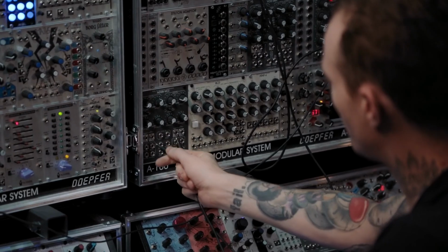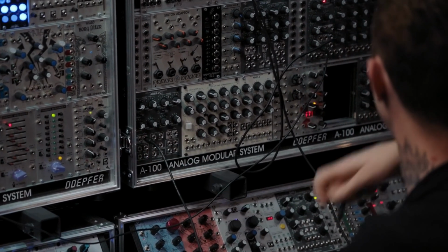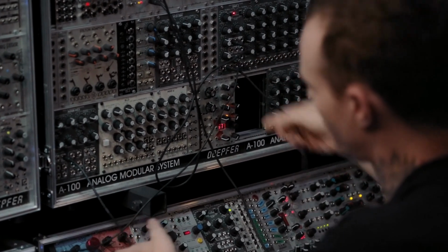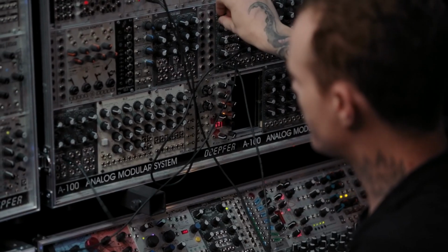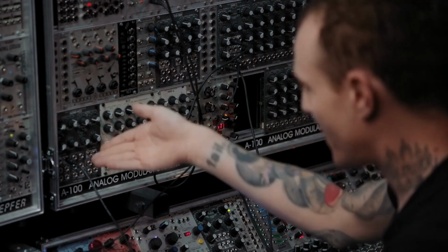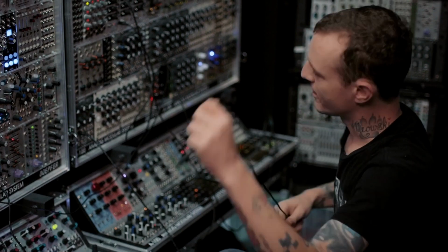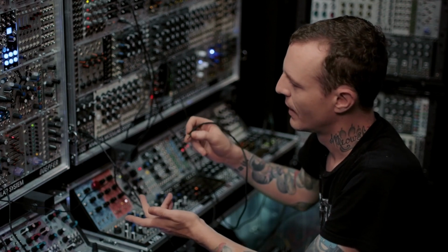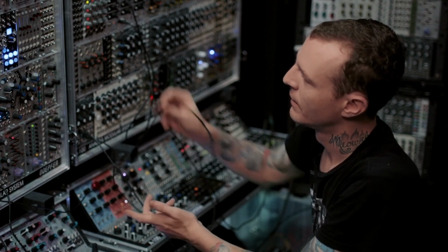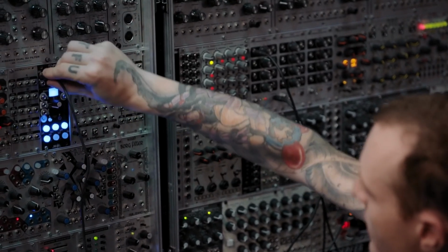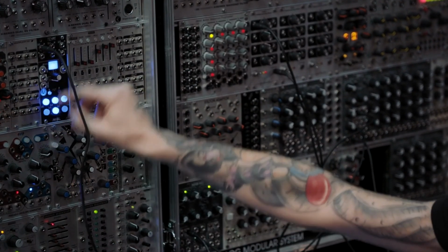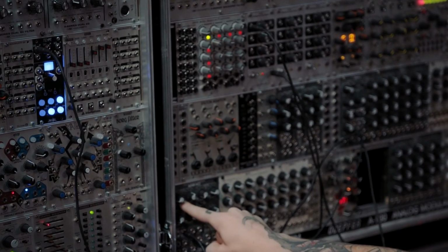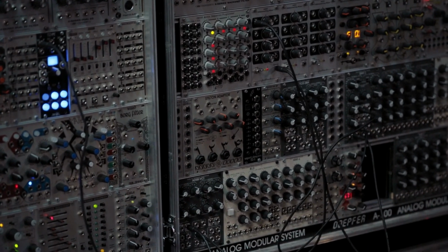But now we'll take the value of that envelope and go into the cutoff parameter, which is called control modulation, which also runs over voltage. So what I'm going to do here is I now need something to trigger that ADSR. So I have to take a gate input to that ADSR, come from, I don't even know. It could be anything. It could be this guy, the Tempe. That's always fun. So now as this channel is blinking here, you can see that that voltage is being sent here and the gate is being turned on and off.